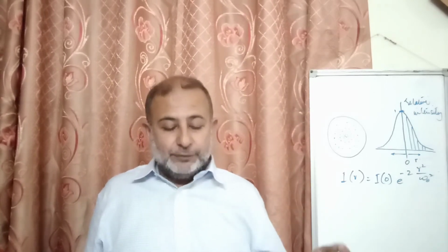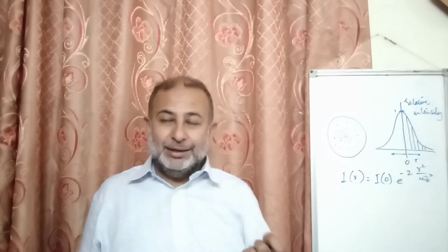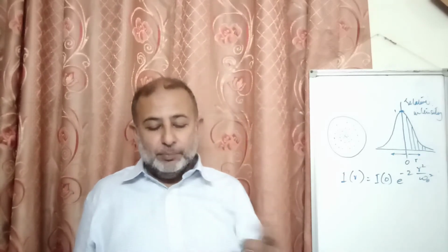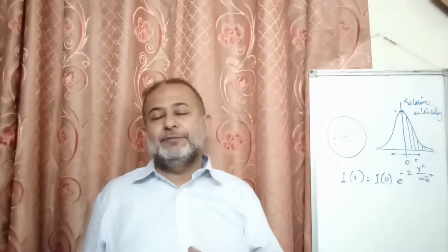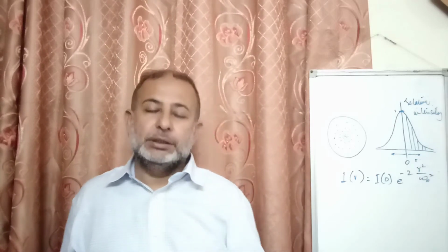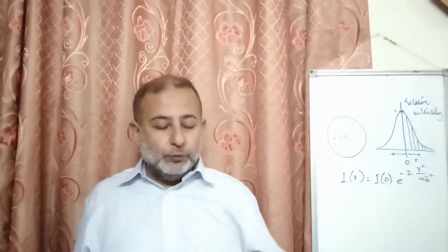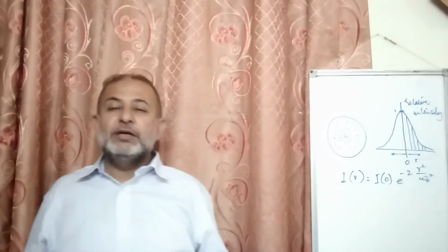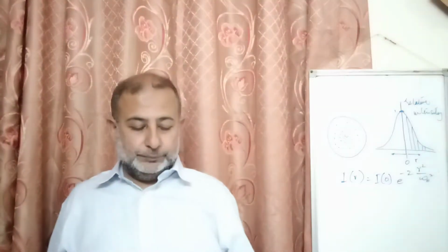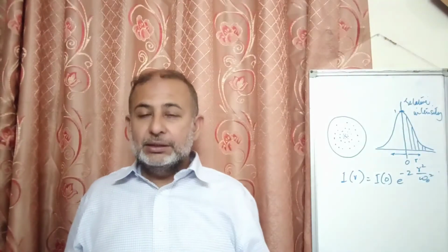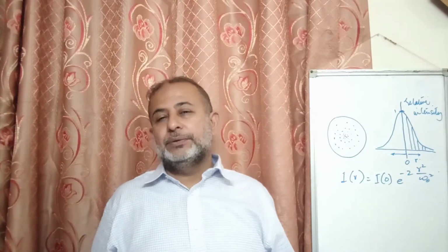The effective refractive index, or N effective, is the combination of core and cladding refractive indices in this particular case. Mode field diameter also depends on operating wavelength. The shorter the wavelength, the lesser the mode field diameter.